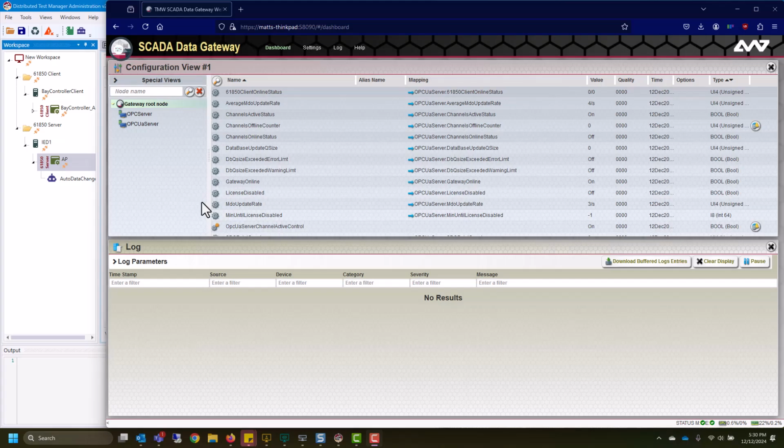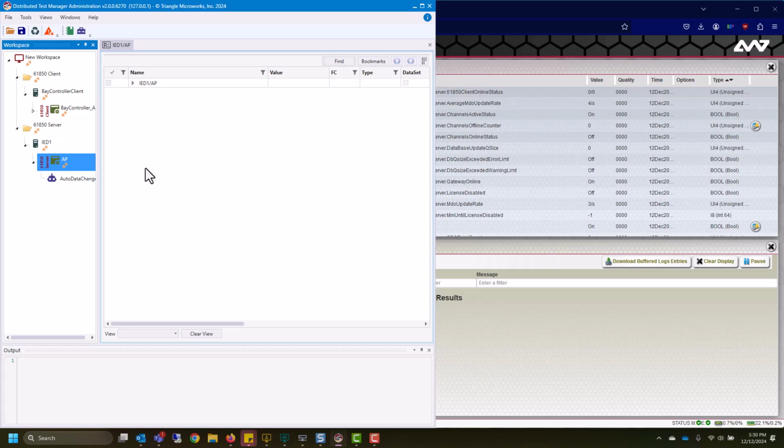In this video, we'll be going over how to configure 61850 in our SCADA Data Gateway. I will be configuring both a 61850 client to get information from our RTU and a 61850 server to present that information up to a SCADA Master. For the sake of this demonstration, I'll be using DTM as the RTU and the SCADA Master.